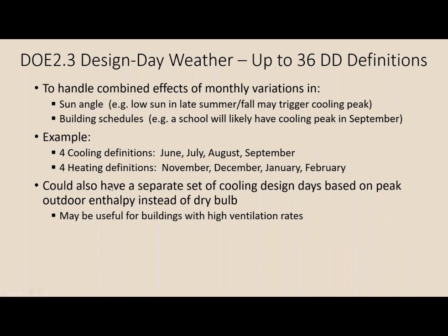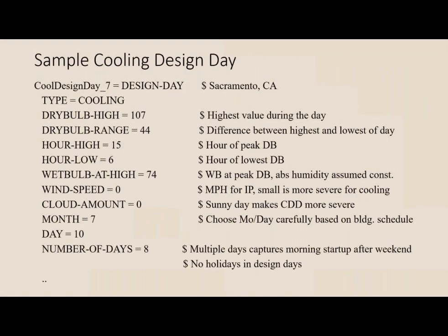The typical design days use outdoor enthalpy as what they call a mean coincident variable, so it's not as intense as the outdoor temperature in those design days; it tends to be averaged. So you might want the primary variable that you're maxing out to be outdoor humidity, and the dry bulb to be more of the mean coincident value.